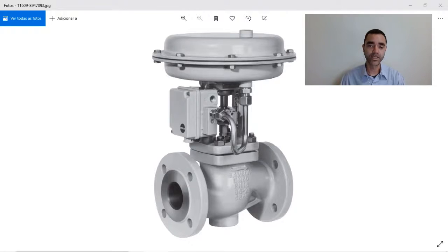On the other hand, you can, for instance, want to control the pressure. So with the same pressure drop, you will regulate the opening, opening more or closing more, to have the desired pressure downstream or upstream of your control valve. You can also want to regulate the temperature. Based on the pressure drop, you will have more flow or less flow, and this media can heat or cool a process, and you will control the opening in order to get your desired set point for your process variable.